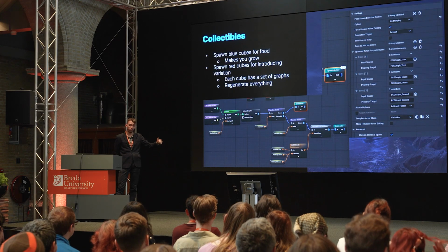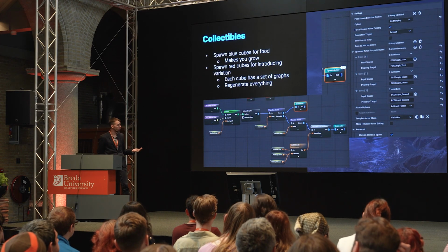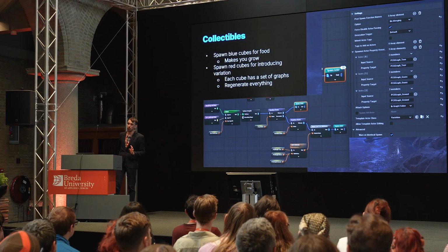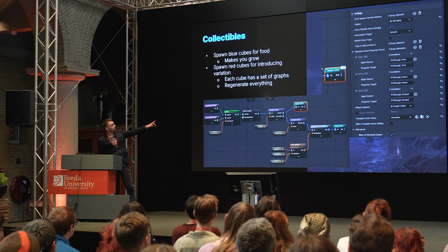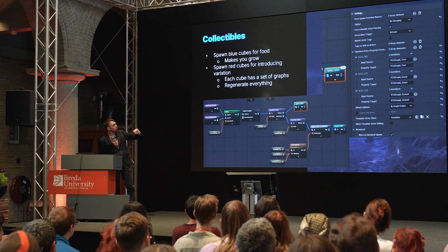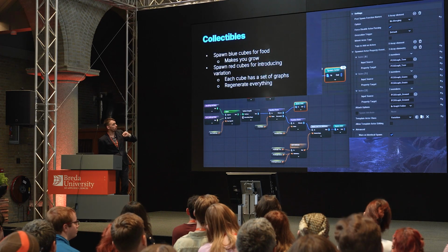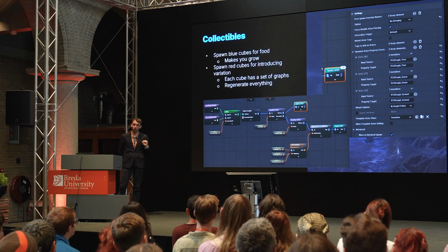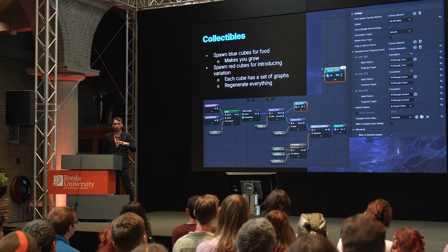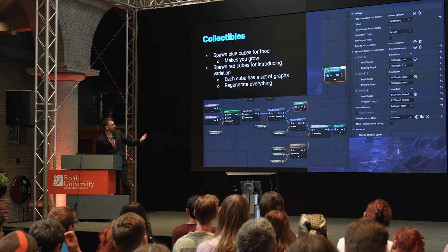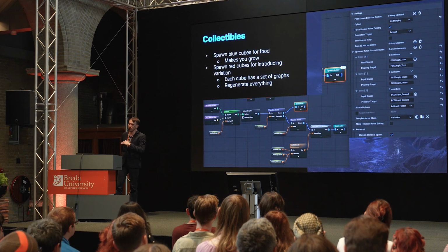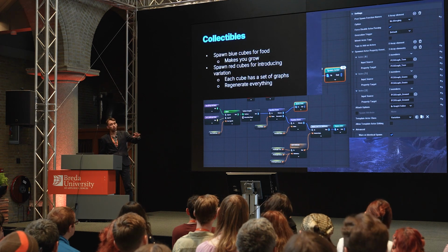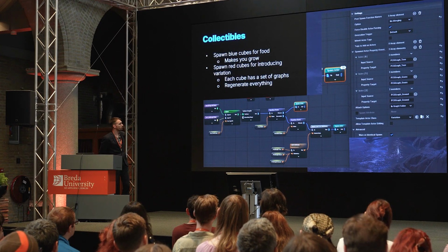So you have one graph for the trees, one graph for the grass, one graph for the ground. Those will be directly pushed to the blueprint that I'm going to spawn. On the spawn actor, you can see the spawn actor property overrides. I have 3 properties on my blueprint, and I will push the attributes from PCG to the actor directly. So that's another way of interaction between PCG and the rest of Unreal: you can send information from PCG to the actors.